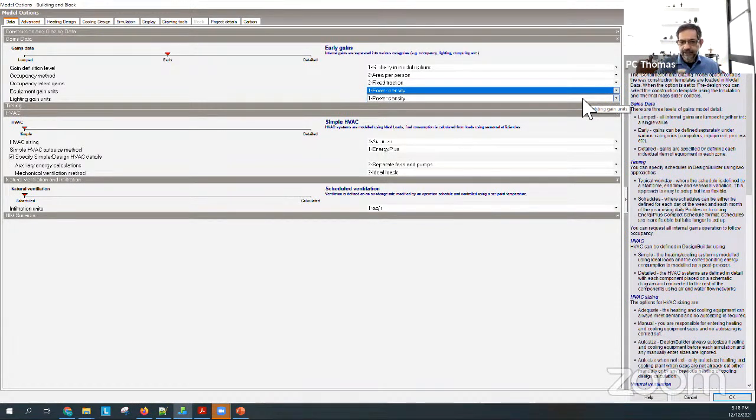Now, in the example that Mansi showed us just now, I remember that for the ECBC Super, the lighting power density, LPD, was 4.5 watts per meter squared. And actually that's what we have in Australia as well for our minimum energy efficiency criteria. So those things you can put there.